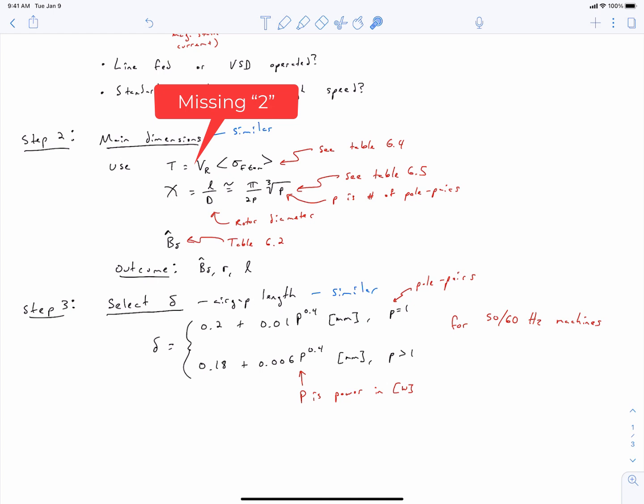The key thing in induction motors is that your air gap length is very closely related to your magnetizing inductance. So you want to have a small air gap length to try to maximize your magnetizing inductance. A high magnetizing inductance is good because that means that you require less magnetizing current to support the magnetic field in the air gap. It means your power factor is closer to unity. A low magnetizing inductance will have a poor power factor, and so that causes your drive electronics to have to be designed for a higher volt ampere rating, so it increases the cost of your motor drive if this is operated by a variable speed motor drive. It also increases the losses in the machine because you have more magnetizing current flowing, so it reduces your efficiency.